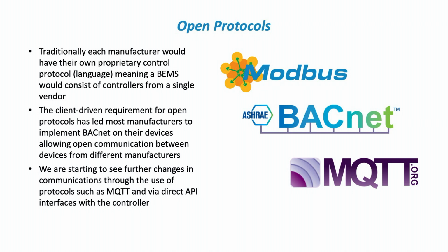We now see it implemented on the smallest of field devices. So if you buy a sensor, then it will typically be able to communicate using the Modbus protocol if it's a smart sensor. With Modbus, though, you need to know what every point in that system is doing in order to communicate effectively. There's also other problems with Modbus.